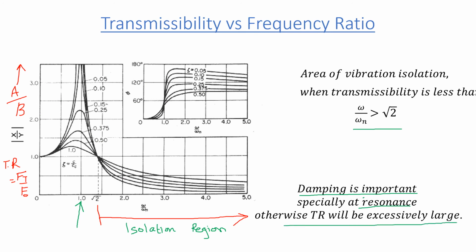So, when we design an isolation system, we introduce a small amount of damping, say zeta. It may depend on the problem, say zeta 0.25, so that if accidentally the system vibrates at resonance, then the damage to the support or base is the least.